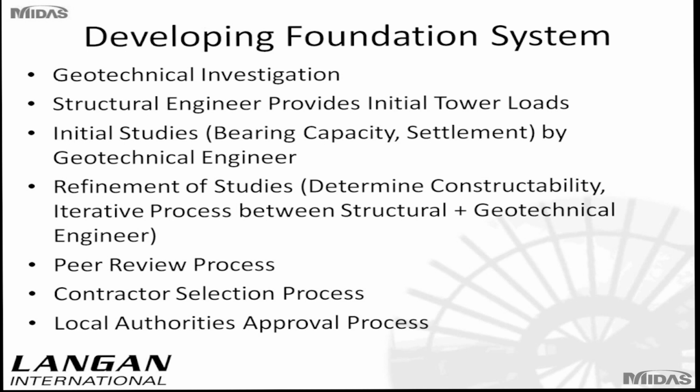Now, the steps to develop the foundation system typically start with a geotechnical site exploration, which involves typically in situ testing and laboratory testing to develop the geotechnical parameters for the design. Then the structural engineer provides initial tower loads, and some initial studies are carried out by the geotechnical engineer regarding the bearing capacity and the settlement of the foundation.